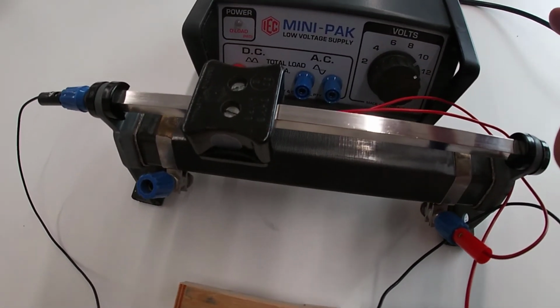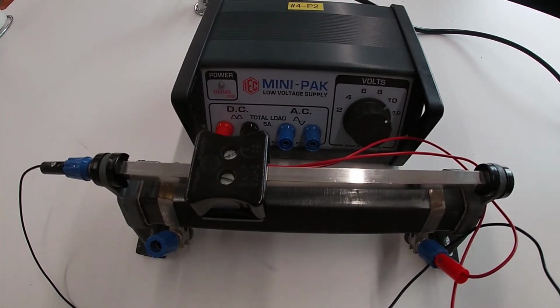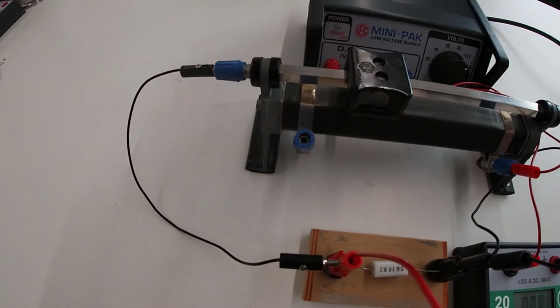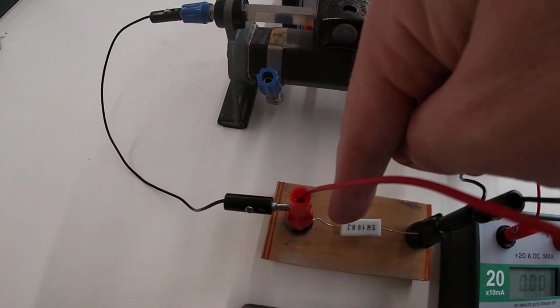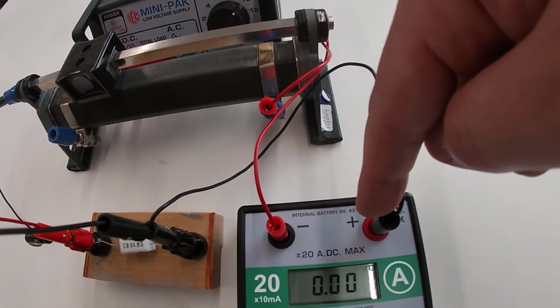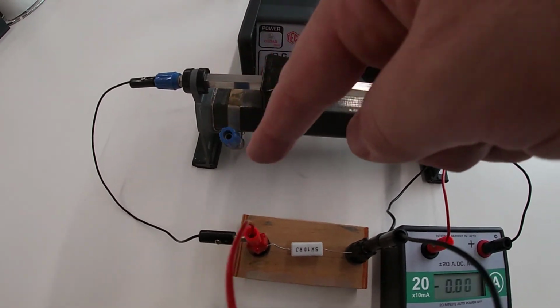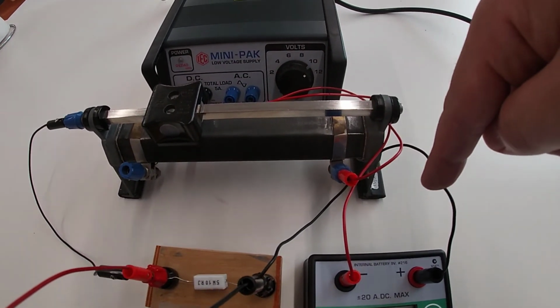This is to allow me to finely tune what this power supply is providing. So effectively, this part here gives me a voltage that I can select, and then it's going to be coming around through this resistor, and then once it goes through the resistor, it's going to be going through the ammeter, and then back to the power supply. So effectively, this circuit is just a power supply going through a resistor with current being measured and going back to the power supply.